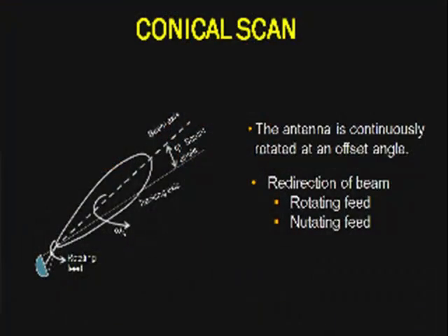In this figure, you are seeing how exactly conical scan can be done. So here we have a tracking axis and the beam rotating axis, what we call the beam axis. The difference between these two directions is the squint angle. So here we are going to continuously rotate the beam around the incoming target axis. For this rotation, we need special feeds.